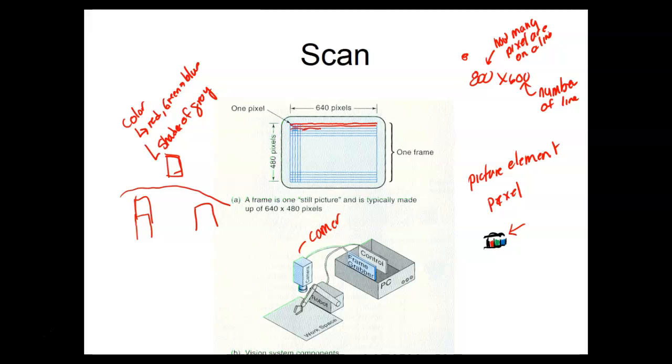I've seen this thing where they have these cameras up here, and they're shooting potato chips across a gap. It took a long time to get there because vision was so slow. Cameras were so slow, with refresh rates of 60 times a second. Now the cameras are really, really fast. They have these cameras mounted up over here, and all these little air jets. When these potato chips fly over, if one doesn't match what it's supposed to match, a little puff of air comes out while it's in motion, flying across the gap, and blows the bad ones down into the gap. They do that with different types of fruit too.